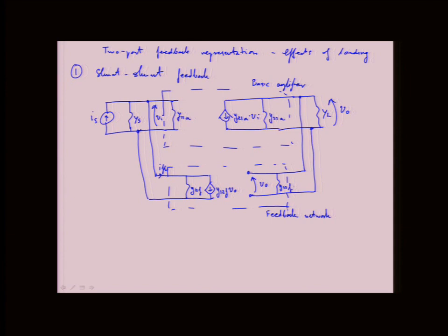And then we're going to have a possible effect that the input actually gets to the output without going through the amplifier. We talked already about that in terms of the return ratio analysis and these topologies where you have this feed-forward path from the input through the feedback network without really going through the amplifier. We have to represent that as another source here that will have Y21F times VI.